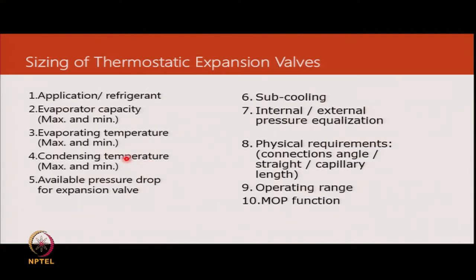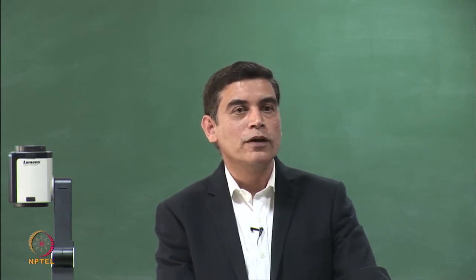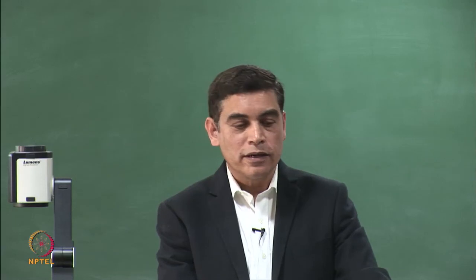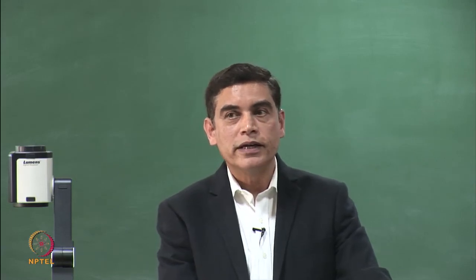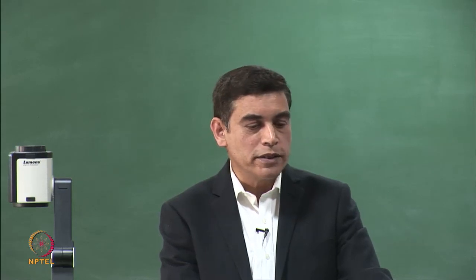And as you see, more and more we get into parameters for selection. Whatever was needed for the compressor selection is equally relevant for the expansion valve, except that we are dealing with some new terminologies like thermostatic expansion valve with minimum stable superheat. We are looking at some circuiting details and all that, but the core parameters that we derived from the pressure enthalpy diagram remain the same and are equally relevant for both the expansion valve and the compressor.